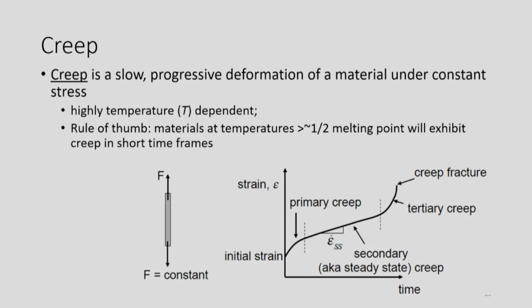But if it exceeds that creep limit, there will be a fracture, or there will be more plastic deformation, right. So it's also highly temperature dependent mostly for compacts and other manufactured materials, but again it depends on other parameters too, thickness, composition, etc.